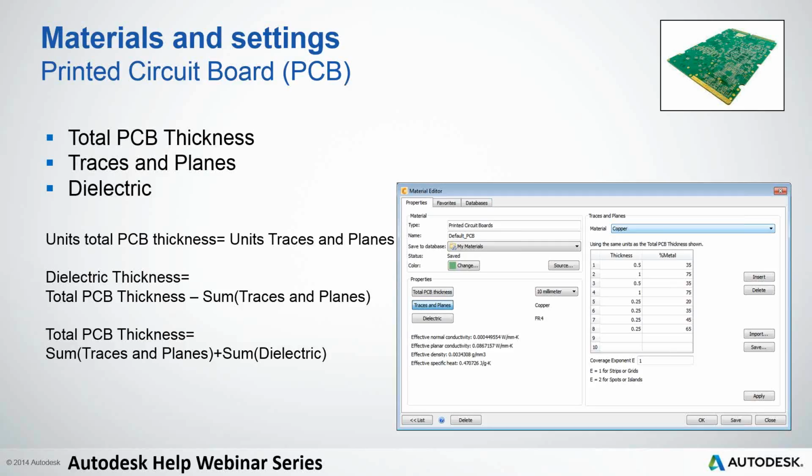So you can see here the first plane has a thickness of 0.5 millimeters and is 35% copper, and so on. Now, when you sum this table, it sums to 4 millimeters, and you know your total PCB thickness is 10 millimeters, so that excess 6 millimeters is actually the dielectric material, which is just the insulator.